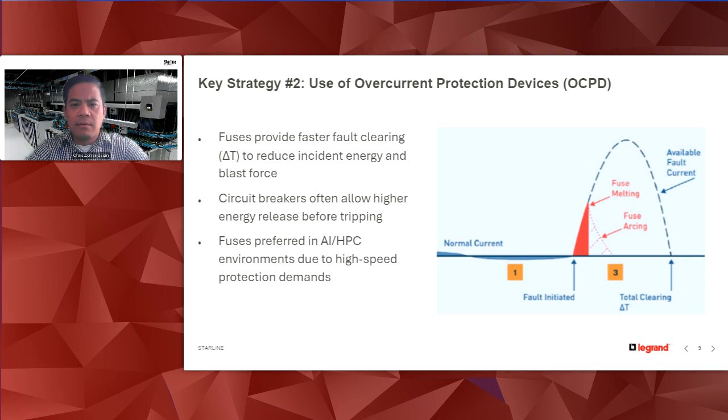And then the other overcurrent protection device change that we're seeing as well, or at least requests that we're seeing recently, is local disconnects at the end feeds. And we're seeing that because, again, in the event of some of these newer cooling methods, a user wants the ability to locally shut off power and not have to go to, say, an electrical room to shut off power in the event of something going wrong. So we are seeing changes in the field.